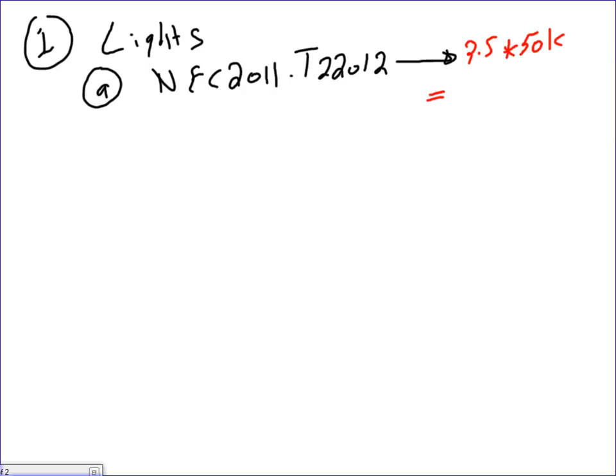If you do the math on this, you're going to find 219 kVA. And please do the math behind me. I might have done the math wrong. So this is your demand for the lights, based on the code, from table 220.12.